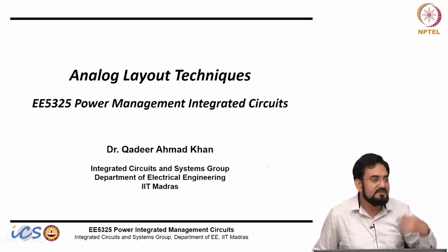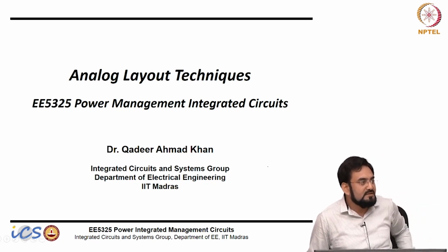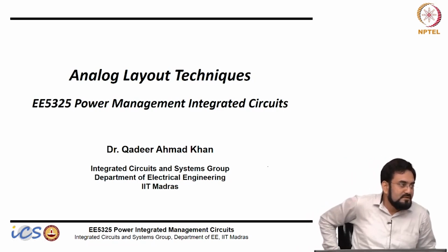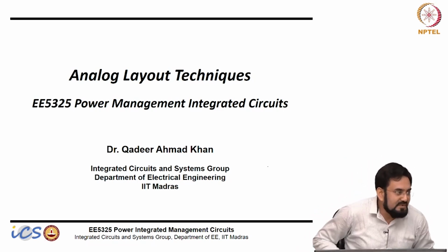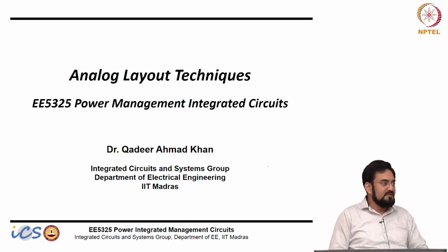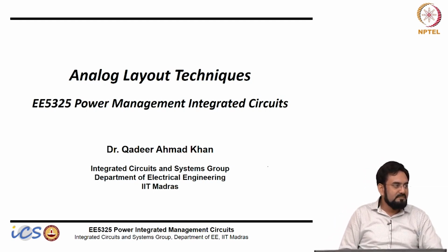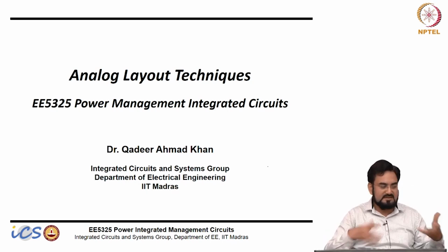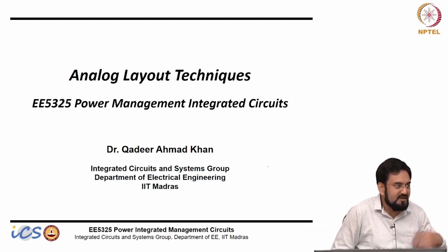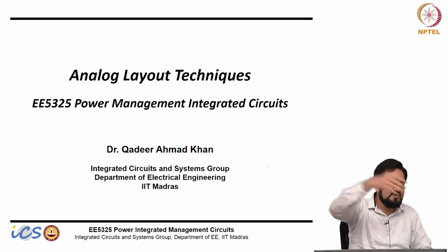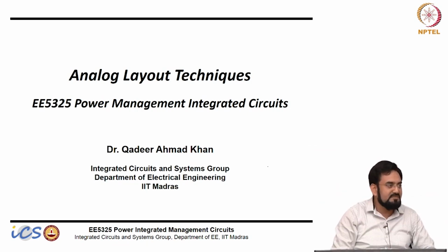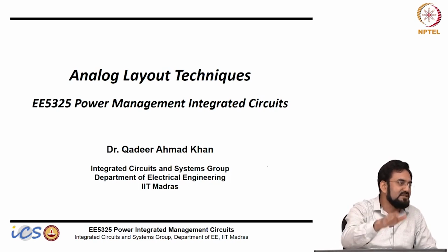No. Anybody else? What is layout? Can you send your schematic to Fab? Fab doesn't understand schematic. Layout tells you how the mask will be created, layer by layer. That's it. Placement, routing, all those, your Fab will not understand. Whether you place it at this corner or other corner doesn't matter for the Fab. It's only the information of the layer mask that will be created.